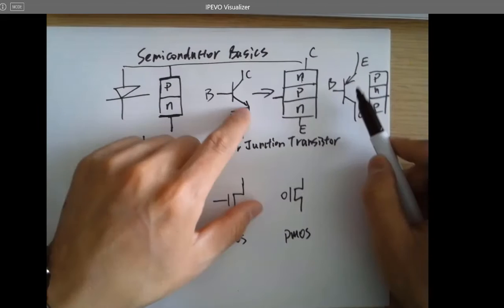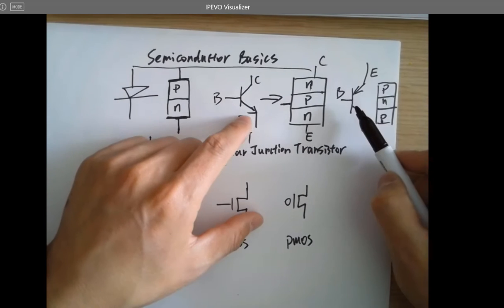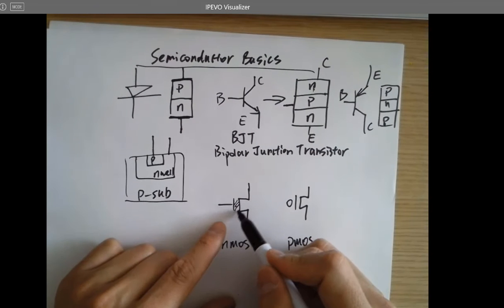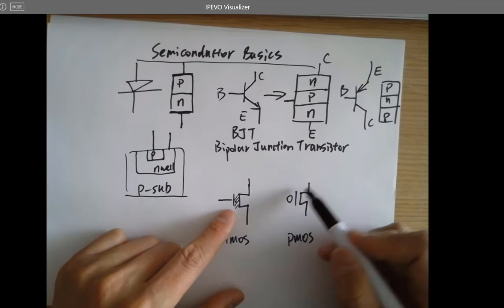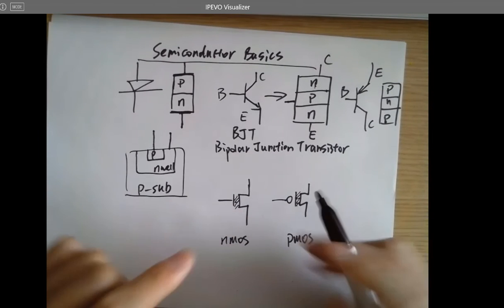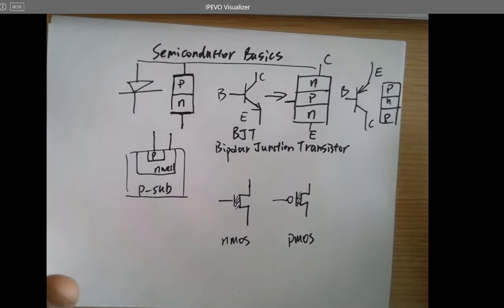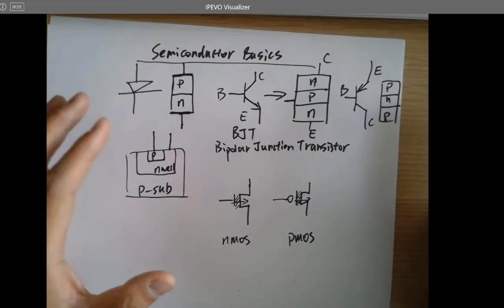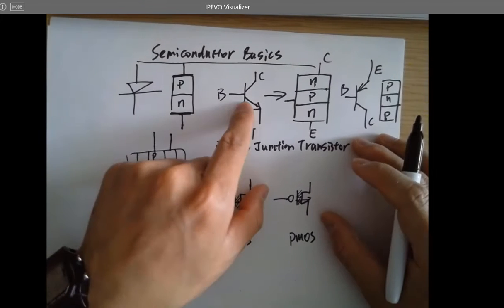So these guys are not being used that often compared to 30 years ago because they consume more power. These ones, there's a dielectric material in between. It's an oxide right behind the gate. So if all the transistors are being put at rest, there's pretty much no power consumption. There will be a little leakage of current into the gate, but it's tiny, in the picoamps level or even smaller. But for these guys, it's different.